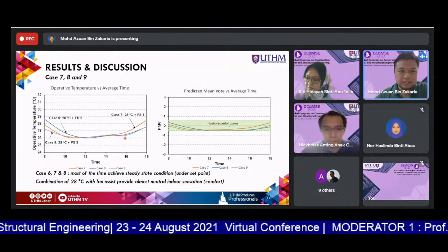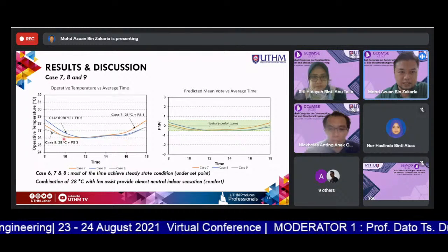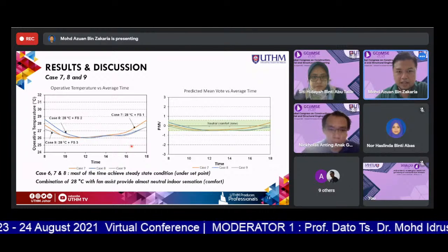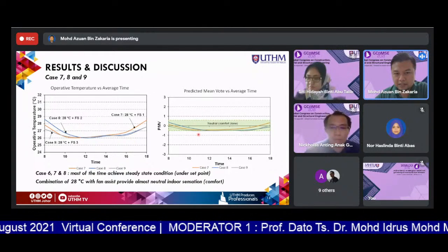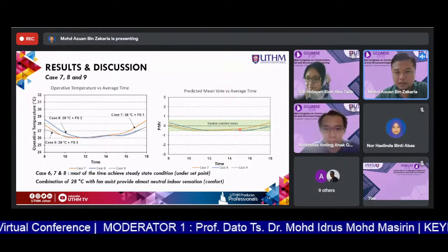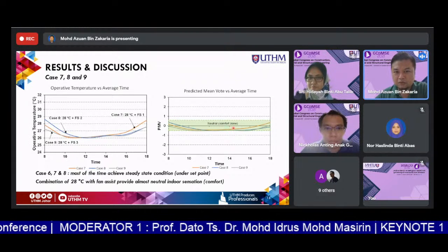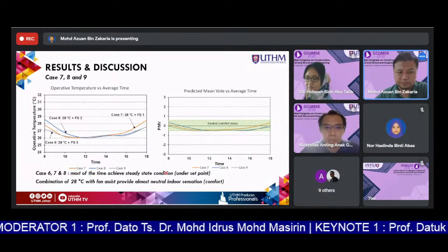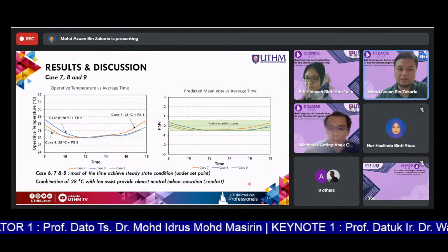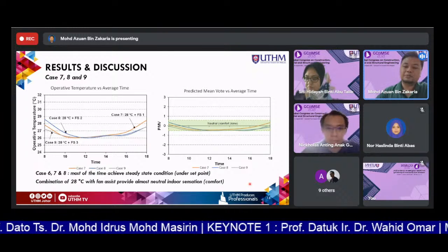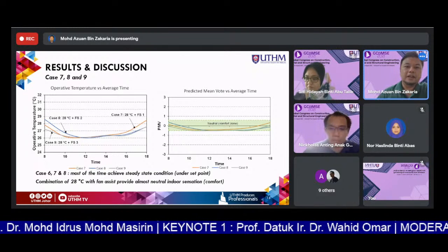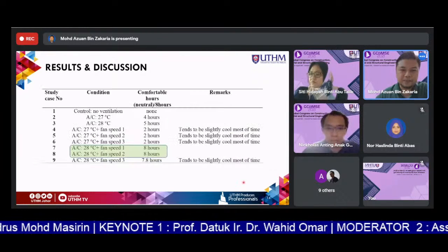As you can see here, it can reach the steady state early, at 10 a.m. And all the cases show very good agreement with the comfort zone. So it means 28 degrees Celsius with fan is possible to be applied. The next slide shows the summary.